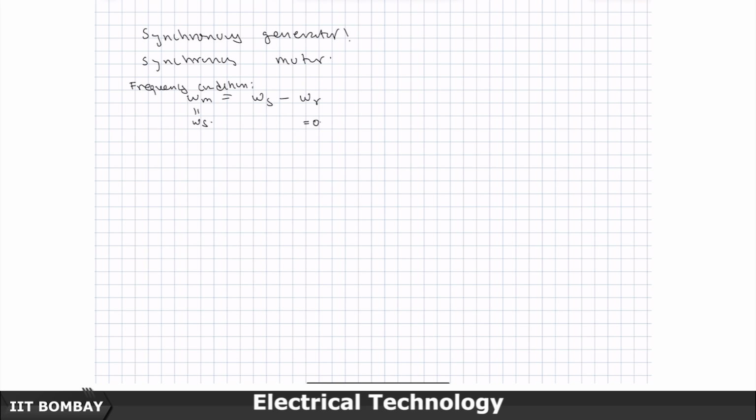So, what happens in a synchronous machine? I have said this again, and it is fine. You are rotating the electromagnet at the synchronous speed. On the stator there are 3 windings, A phase, B phase, C phase. Now comfortably I can say that these windings are distributed in space, and you know why we distribute them in space: because in that case, the spatial distribution of the MMF due to any winding is sinusoidal in nature.